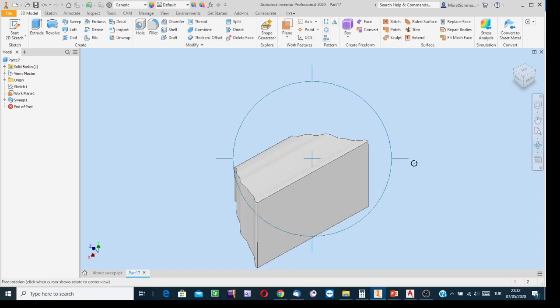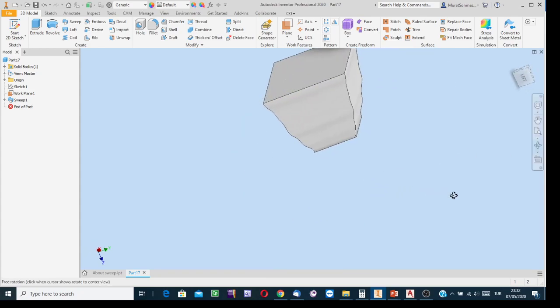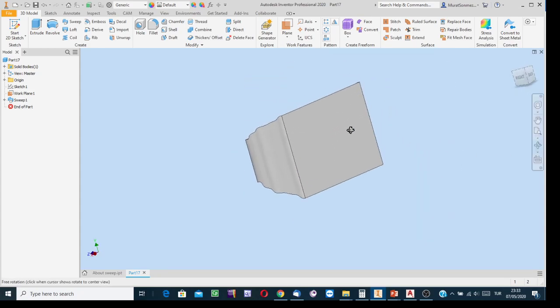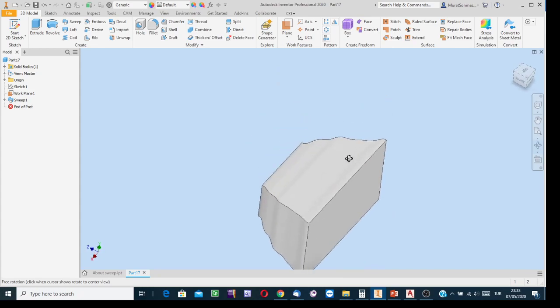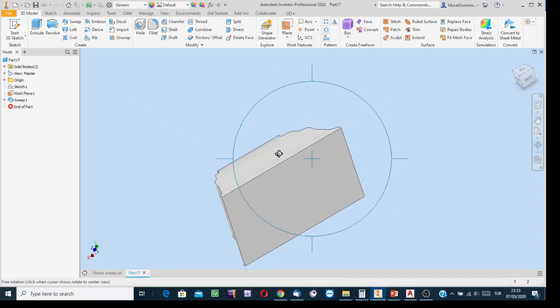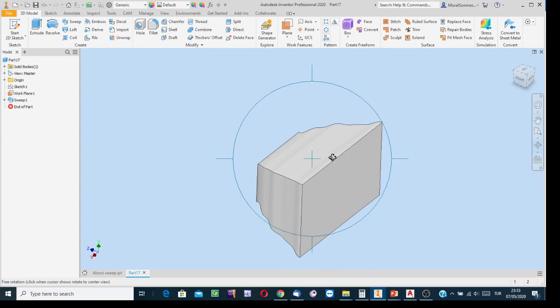And then here is the strange object. It is by definition a loft, but since the cross section is the same in shape, only the size changing, use the sweep creation tool, via which you save time.